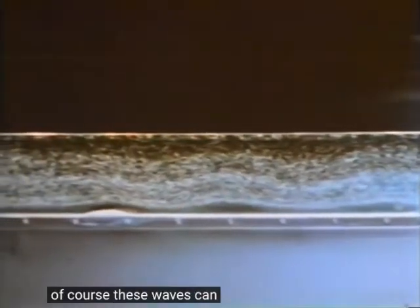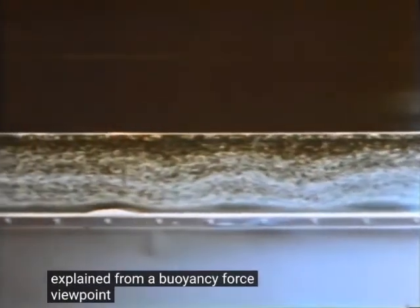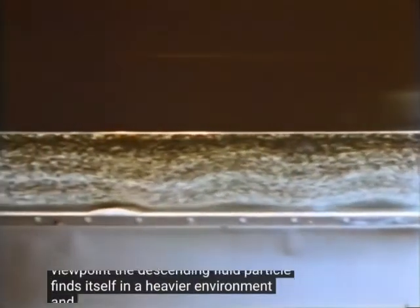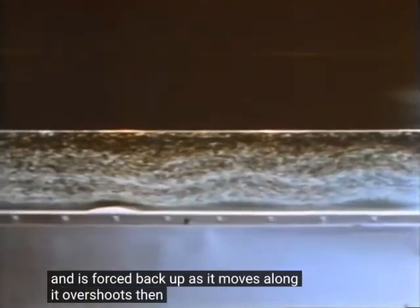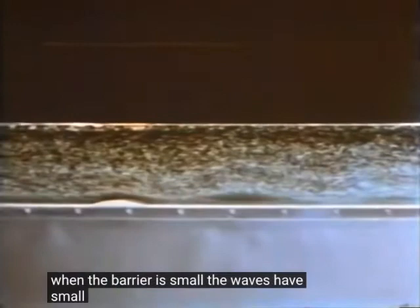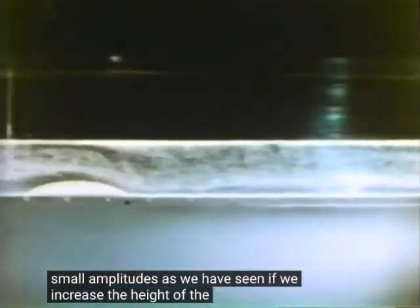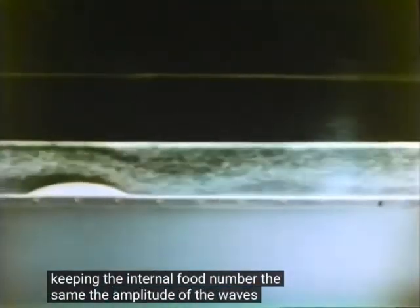Of course, these waves can also be explained from a buoyancy force viewpoint. The descending fluid particle finds itself in a heavier environment and is forced back up as it moves along. It overshoots, then descends again, and so on. When the barrier is small, the waves have small amplitudes, as we have seen. If we increase the height of the barrier, keeping the internal Froude number the same, the amplitude of the waves gets much larger.